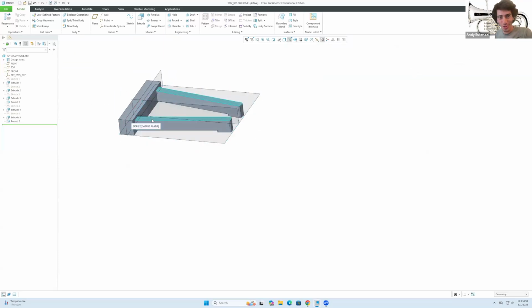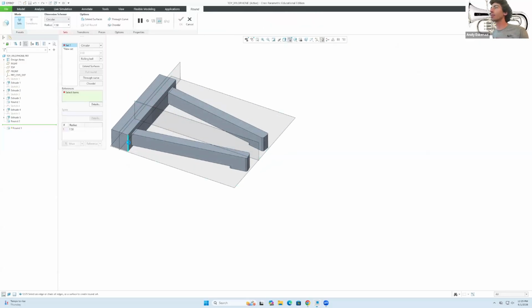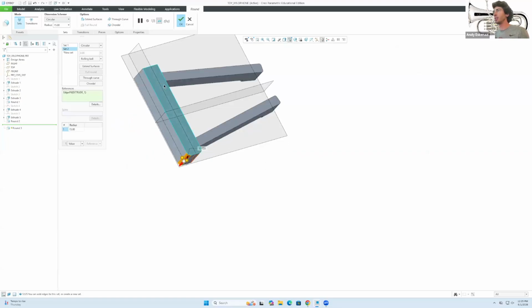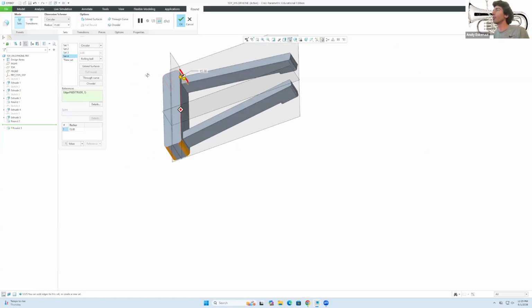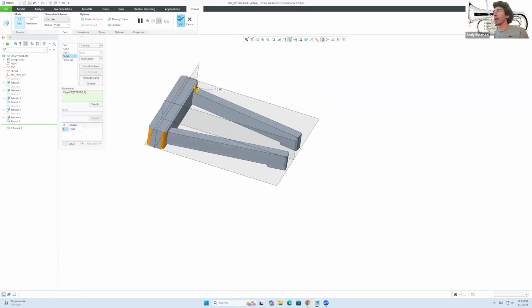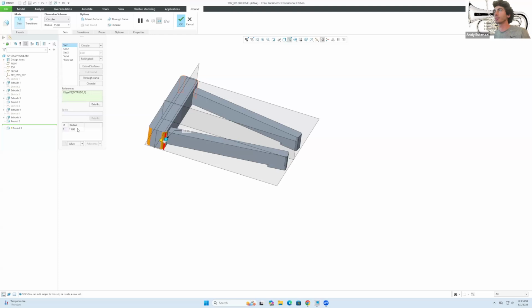So we're adding slowly details to a little xylophone. So now I'm going to go here to round and select, for instance, let's do 15 as an example, right? You see how 15 is now the one that's going to be replicated on all the other ones that come later. But now, if I were to edit the definition in here, and I change that to 20, only that one is going to change. So that's one thing to bear in mind.